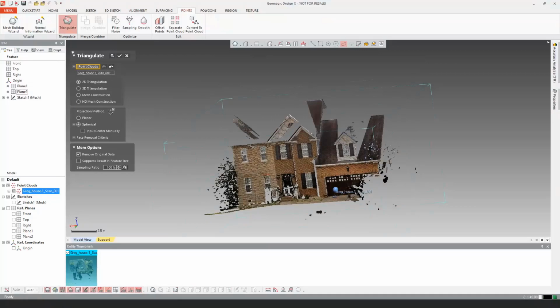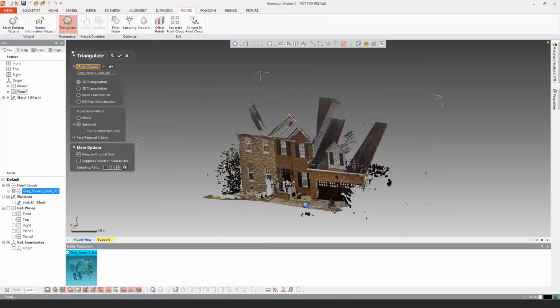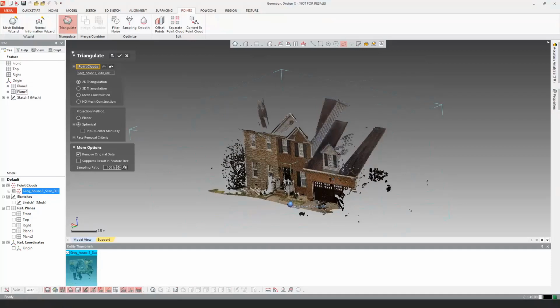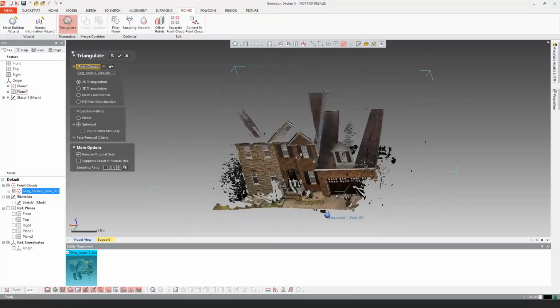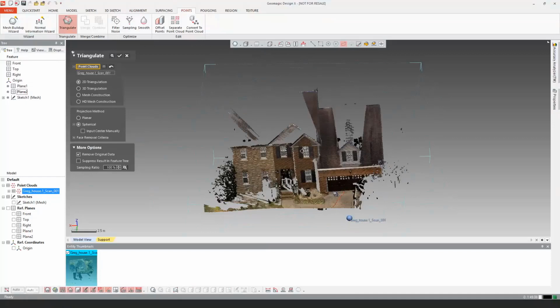and you will notice when you run stuff like this 2D triangulation and this method, some things of high incidence angle, like leaves on this tree where the scanner was hitting them pretty flat, they will get edited out of the scan data essentially, because it'll say the accurate positioning of something like that with such a high degree of incidence to an almost planar tree leaf that's in the wrong direction, or the top of a banister or something like that, isn't necessarily going to be an accurate measurement. So it could pull some stuff out like that for you, and it's very handy if you have a lot of scans in some very complex geometry.